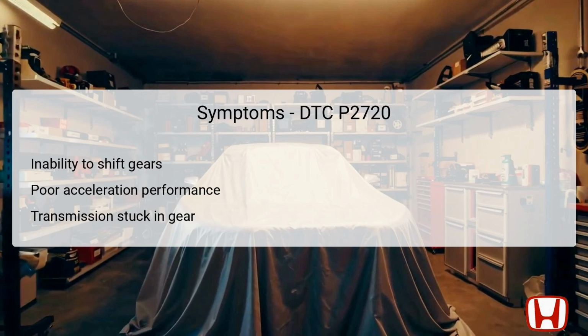Many drivers may also feel a delay in the responsiveness of the vehicle when attempting to accelerate, which further compounds the issues. Additionally, if the transmission remains stuck in one gear, it can lead to increased engine strain and potential long-term damage. Identifying these symptoms early is key to establishing the correct repairs and ensuring the vehicle remains in optimal driving condition.